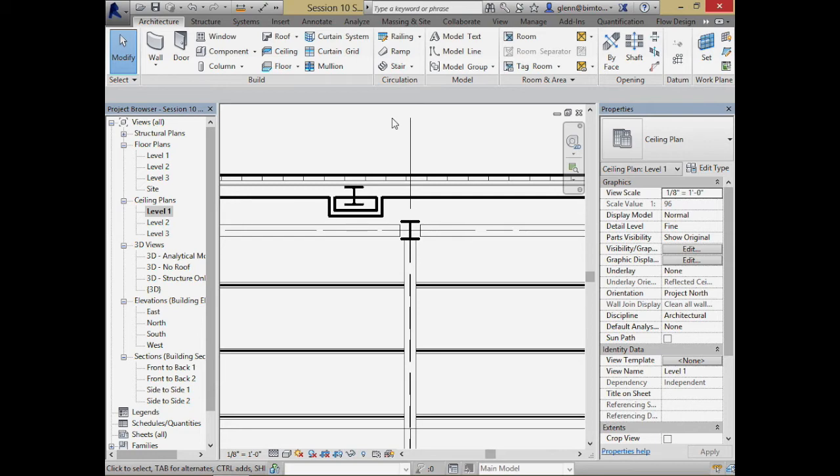And in a lot of older construction, you find that in block wall construction, you find it in a lot of old masonry construction. You find these things where the beam's coming down on what looks like a column that's buried alive in the wall. Okay, there may be a steel column in there, it may just be a thickening of the wall surface itself. But that's what happens when they come together on the wall. So you can have it completely embedded in the wall, completely independent of the wall, or halfway between. And it really just depends on how much flexibility you want.